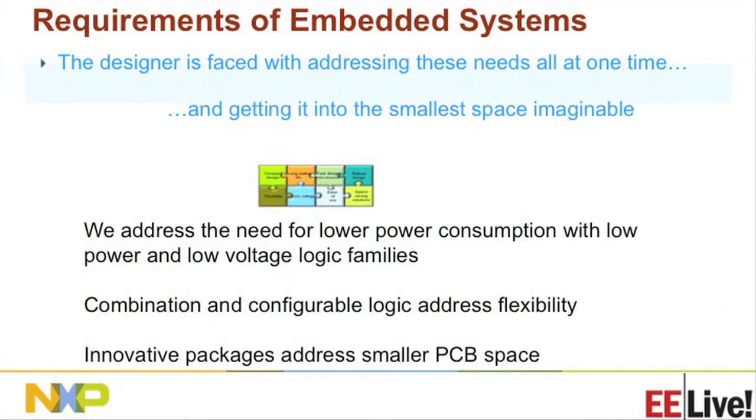So we address the need for low power consumption with our low power and low voltage logic families. So we have 3 different families: LVCs, AUP, and AXP logic for this purpose.